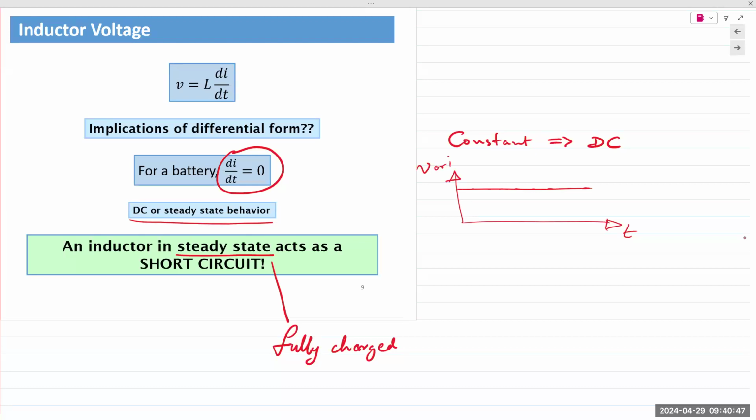After this point, or actually even before that point, the magnetic field that is set up creates a back EMF, or it creates a voltage that has a polarity that is exactly opposite to the current that is actually flowing through the circuit. Okay, again, I'm trying to stay on this side and not jump into the physics. So current flows to the inductor, sets up a magnetic field.